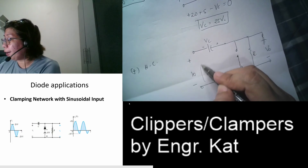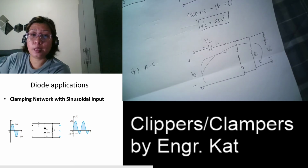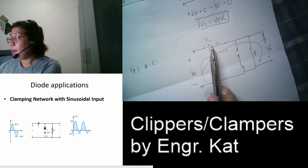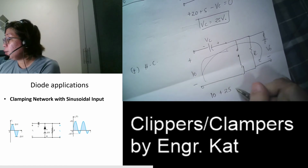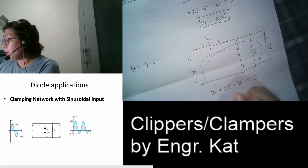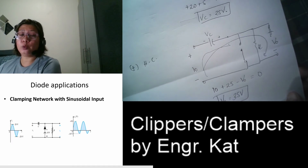So if we have a loop there outside, that will give us plus 10, plus VC, but VC is 25. So plus 25 minus VO is equal to 0. So what is your VO? VO is 35 volts. Then we need to draw the output and the input.